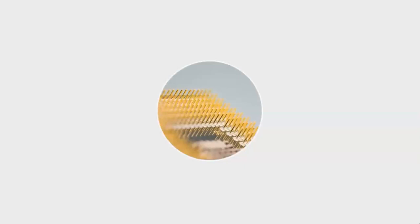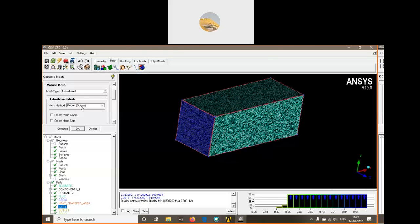So what we can do is, I'm just going to create my volume mesh. So go for compute mesh. Now guys, first I used Octree. Now I'm going to use Delaunay. The thing is, if you don't have any mesh, then Octree works fine. If you have a surface mesh, then Delaunay works fine. So I'm going for Delaunay. Click compute. So let us give some time.